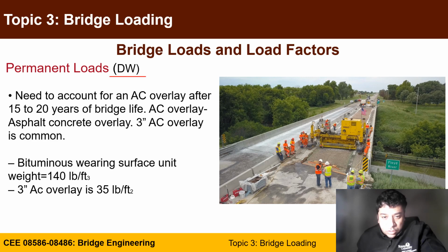DW is related to what we call the future wearing surface, an asphalt concrete overlay after 15 to 20 years. So every 15 to 20 years, we have to rehabilitate our bridge decks and add a future wearing surface in terms of asphalt or concrete overlay.